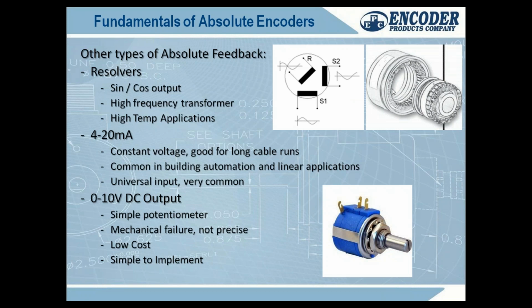They're basically an analog feedback. You're inducing a current into one coil, it excites these coils, and then you read the output of the excited coils. And it gives you a position. It's as accurate as you can reduce noise, which is its drawback, it's incredibly susceptible to noise. But resolvers do have an advantage. They can go to about 210, 220 C. Most encoders out there melt at about 130 C.